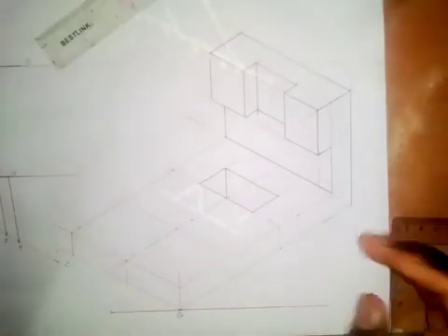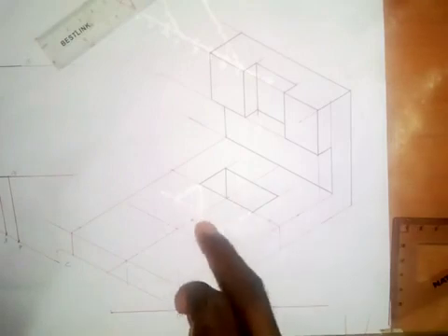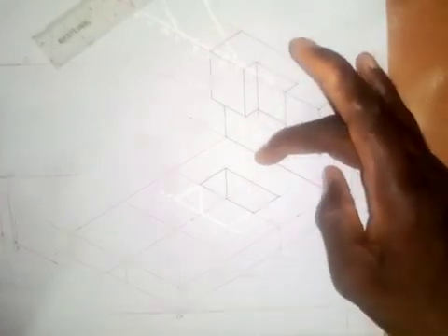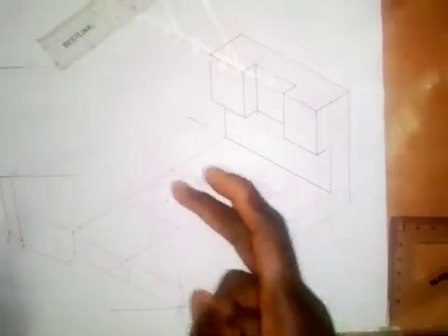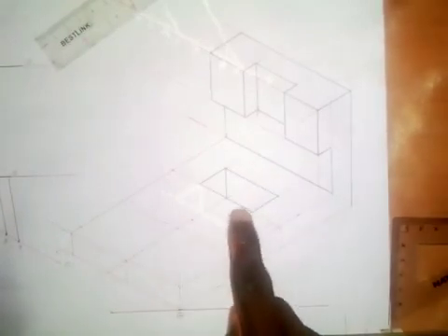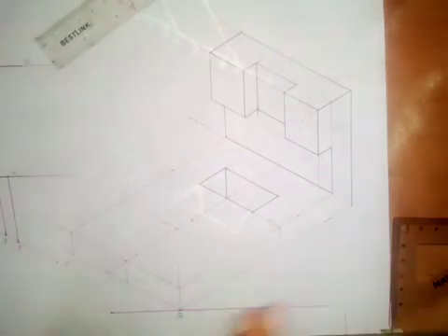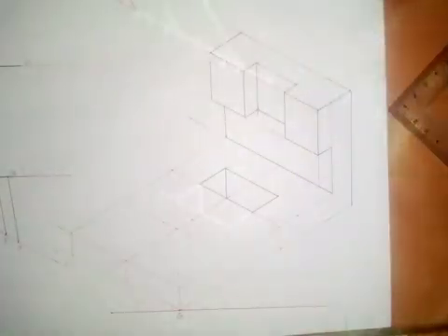All right, so there was a mistake in where I placed the rectangular hole, but I've taken it to where it's supposed to be. So this is where it's supposed to be. What I did is just that I cleaned what I have on this part and I left this line. So I have to take 20 millimeters backward. So that's the mistake. So let's move on to construct the circle. As I said, the diameter of the circle is 40 millimeters, the radius is 20.